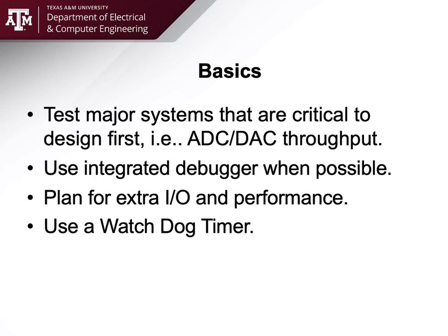Of course, just going back to what we talked about earlier, test all major subsystems for your system first. Your A to D, your D to A converters, any temperature sensors, all the core functions, timers, counters, whatever it may be, peripheral PWM. Test each of those subsystems completely separately first before attaching it to your main function. Write simple, basically hello world tests. Literally prove the communication systems work by doing a star thrower where you send out asterisks.